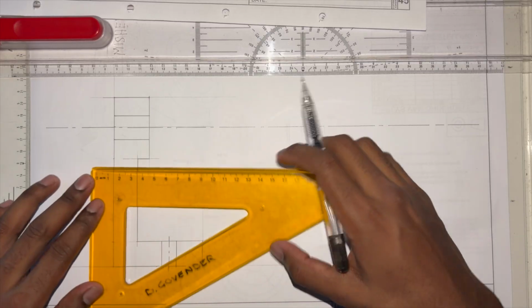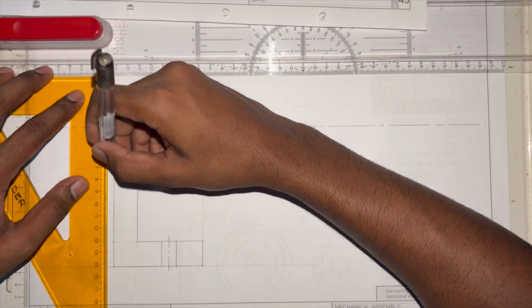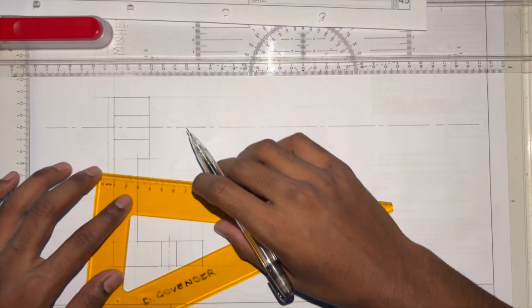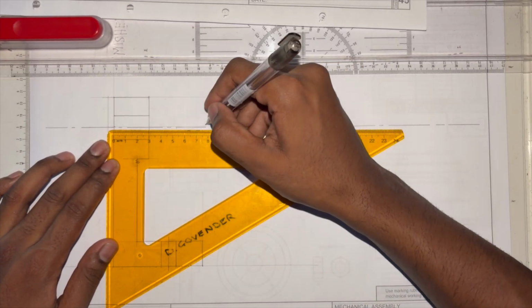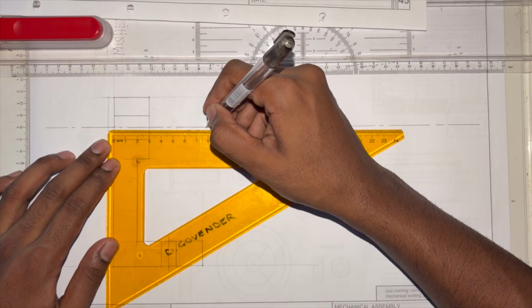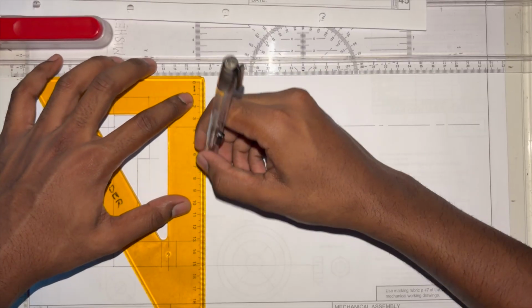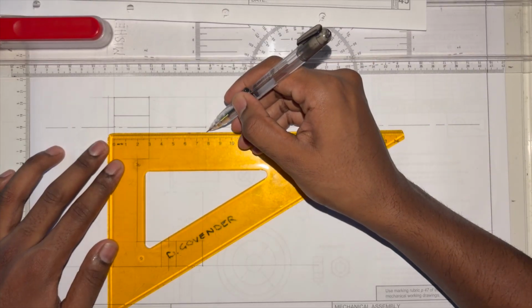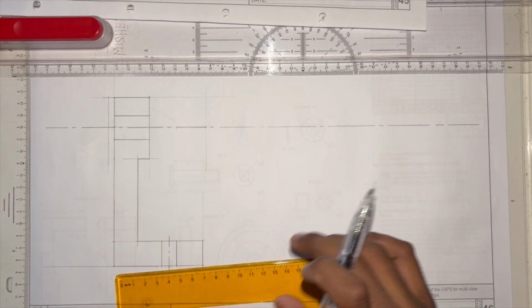Okay, I said I'm going to draw the shaft next, which is what you should do. It's 5 millimeters out of the back of this bracket. It sticks out 5 mils. Then it measures 78 from there. Okay, 78. And that's the end of the shaft, right? I'm just going to double check. Sometimes I make mistakes here. Okay, 78. There we go. That's the end of the shaft. Starts here, ends over there. Very small shaft, very short in length.